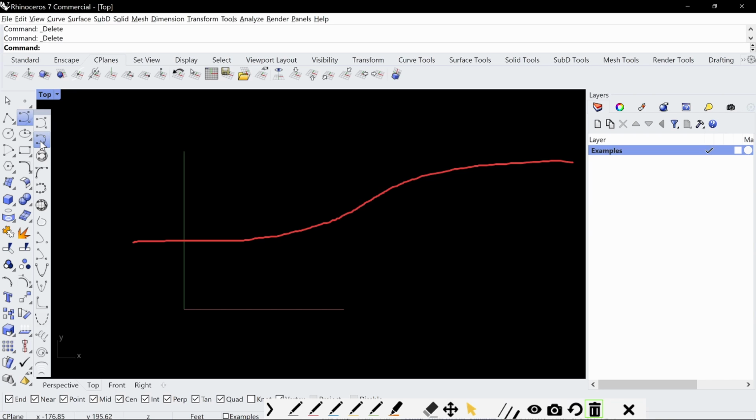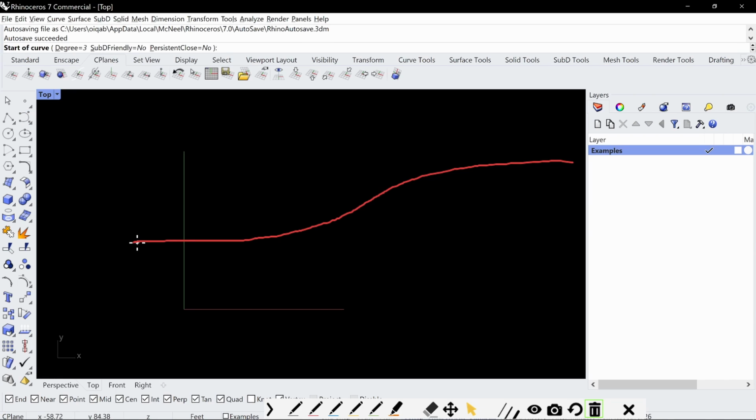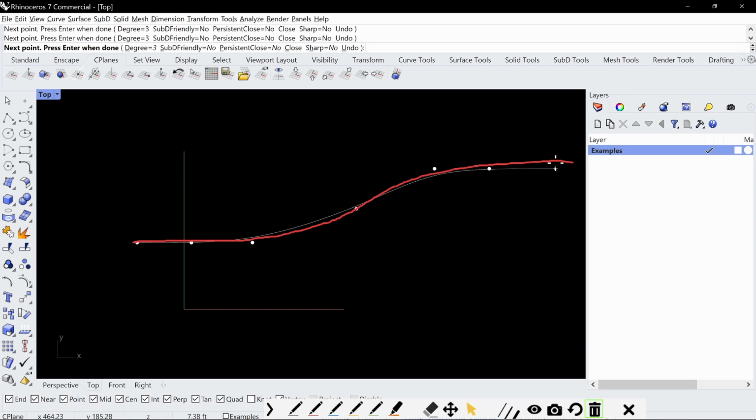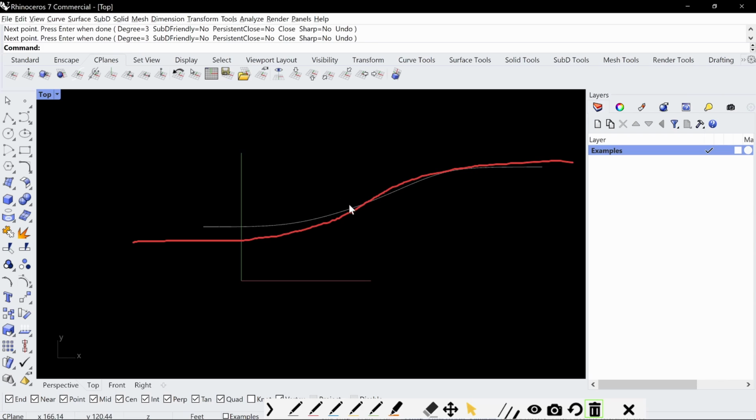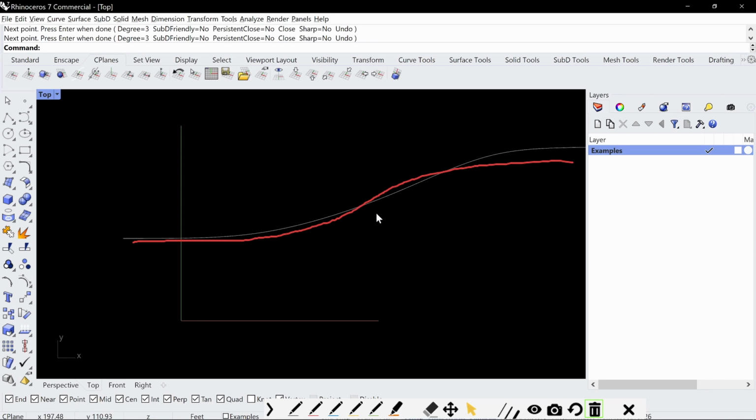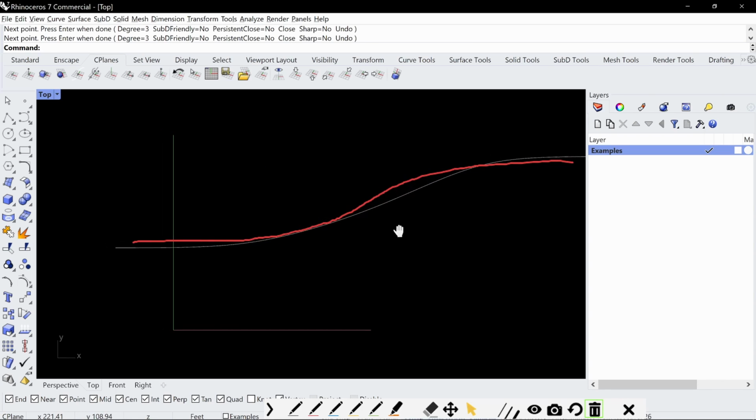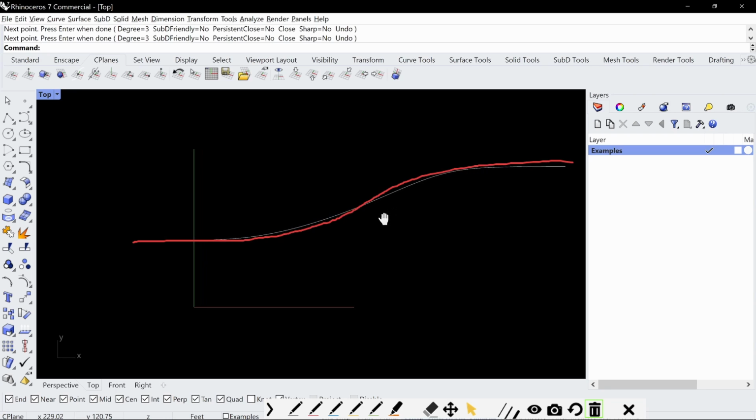whereas curve interpolate points will literally curve or bend at the locations that you click on. So for example, if I go here, I can click 1, hold shift, 2, so you probably want 3 points to keep this flat, and then my middle transition point right here, and then I'll go back to the top, and then 2, like this. And so I zoomed out a little bit, and I can go in and modify this curve now if I wanted to follow this.